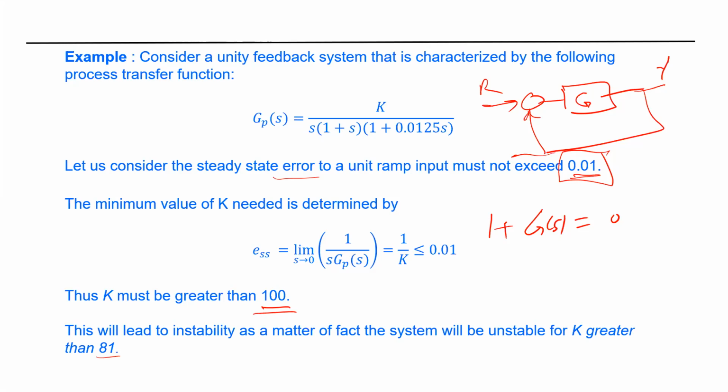I just want to tell you what relative stability means. So in the sense of, if we want to do the test in Routh-Hurwitz, we will be seeing how far we are from the j omega axis. While in the Bode plot and Nyquist, we will have an exact procedure to determine how much I can add to my system in terms of the gain before it becomes unstable.